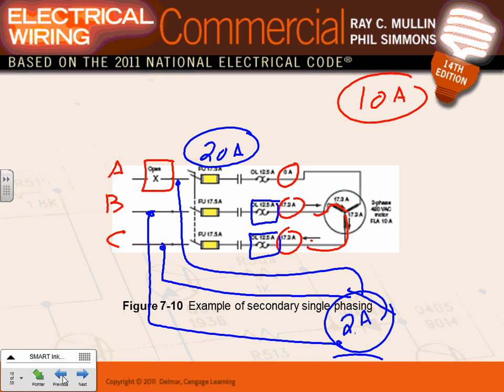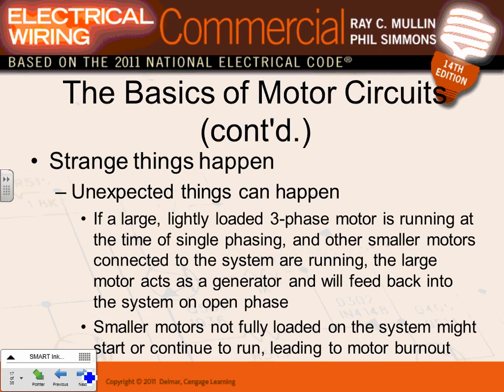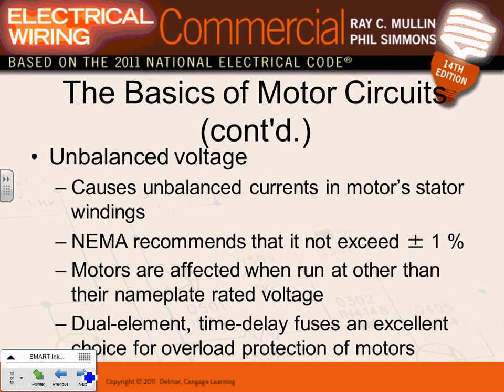So long story short, if you have single phase condition, your three-phase motor continues to run. If it's half loaded, it will continue to run, and it will actually generate the phase that's lost for other smaller motors to start and run. So just be aware of that one. I know you guys are not maintenance guys, so that's what strange things happen.